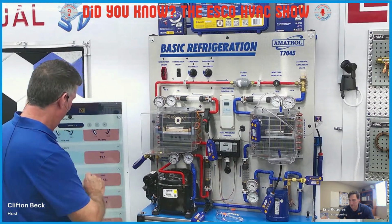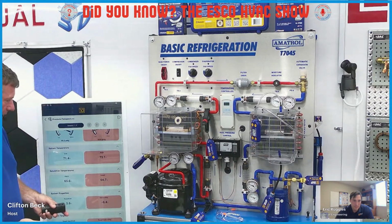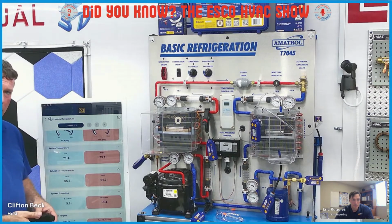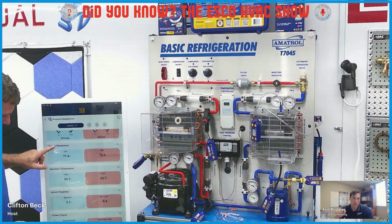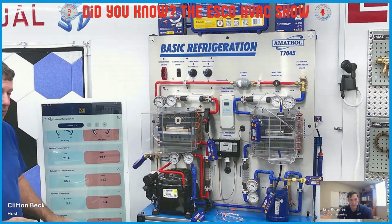Yeah, you should just need to push it. Yeah. So now we have pressures and temperatures. Looks like your system's equalized, so it's not operating right. So temperatures are the same, pressures are the same. Superheat and subcooling don't really tell you anything at the moment because it's not operating. Right. But at the bottom of the screen, it's hard to see with the camera at the moment, but there's system targets, and that's your target superheat and target subcooling, right?